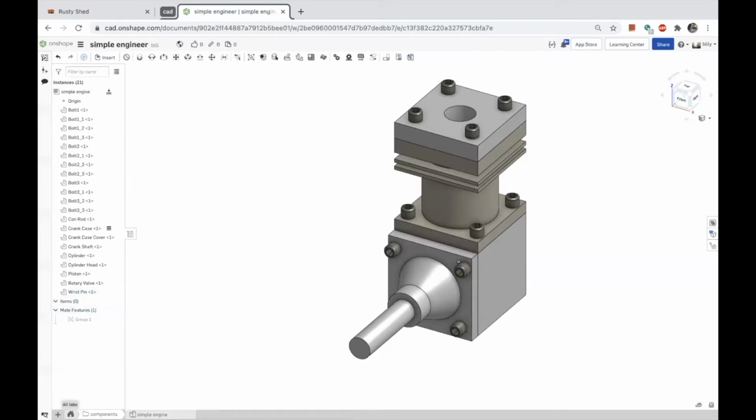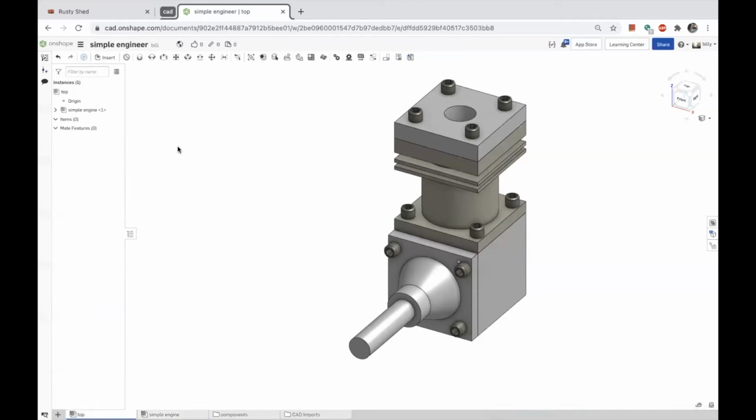Typically what I end up doing is, here's my part studio. I will always take a part studio and have an associated assembly, and all it does is collect all the parts in that part studio. Then I take that subassembly and put it into my top, because it keeps things clean.